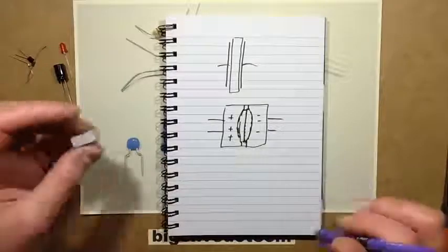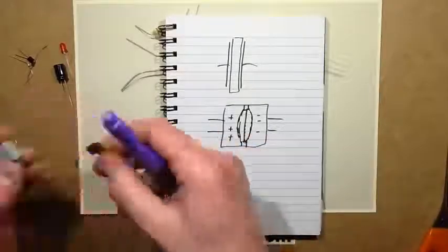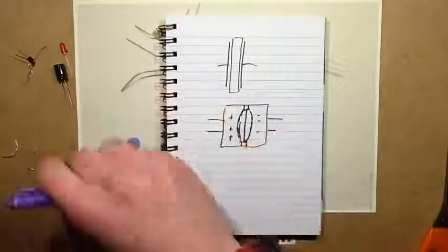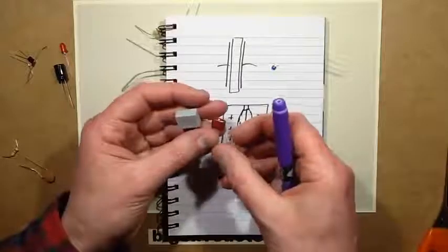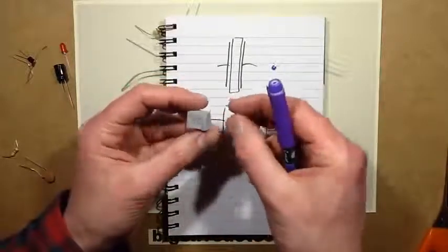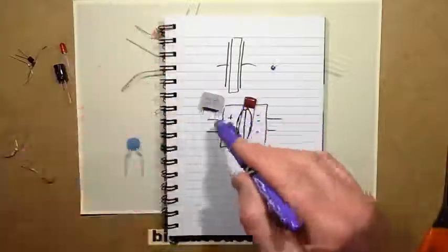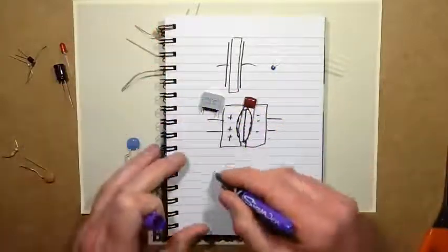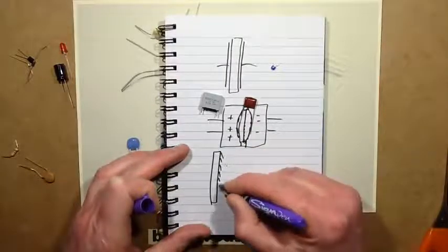Where you're going for a high voltage capacitor, the size has to go up. These are also 100 nanofarad. So you look at this one, it's 100 nanofarad, it's really small, but it's a low voltage one. When you're increasing the voltage, you have to increase the thickness of the dielectric, the insulation between them. To make this type of capacitor, these are metallized film capacitors, it's a film that's metallized on one side.